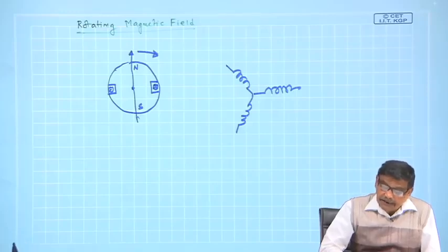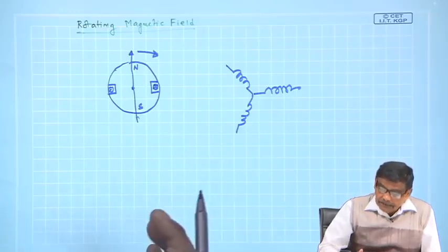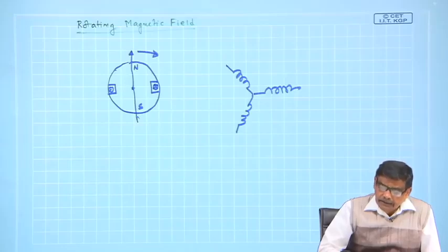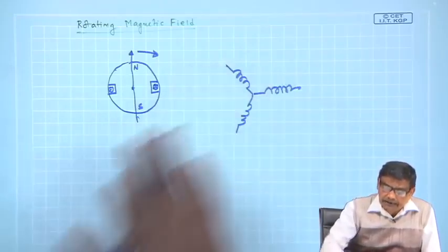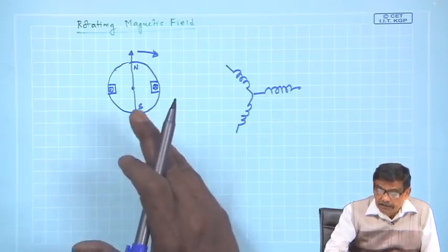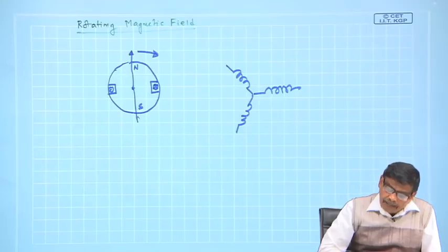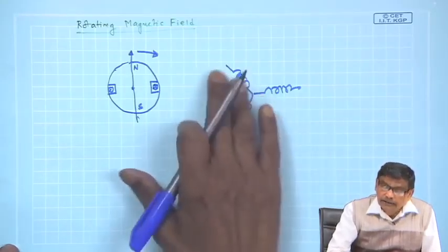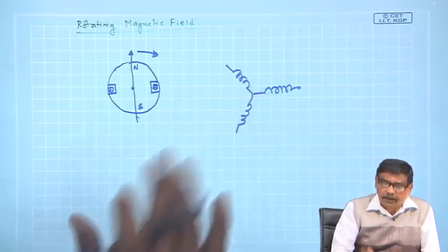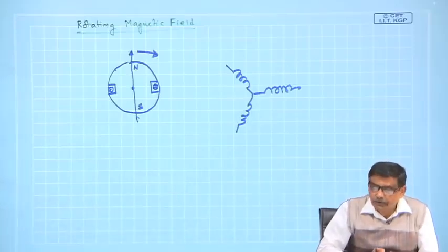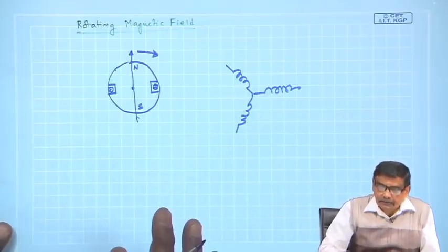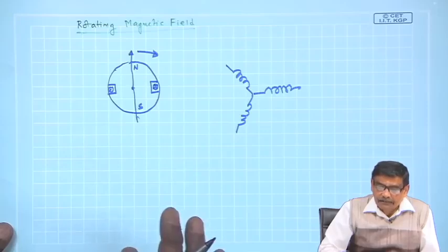He demanded that a balanced polyphase winding is made, and mind you, 3 phase is a polyphase winding. If you have a balanced polyphase supply, 3 phase suppose, and you excite, and these coils are stationary on these slots, you do not move anything, you do not ask for any prime mover or things like that.